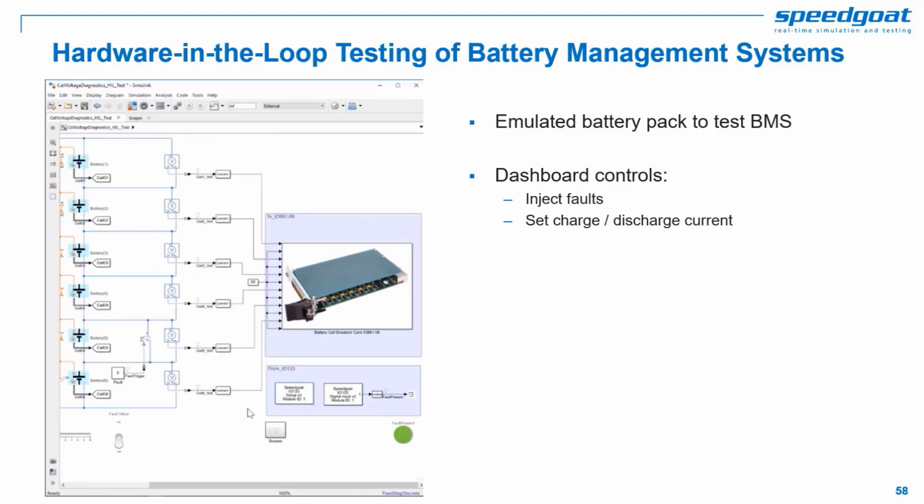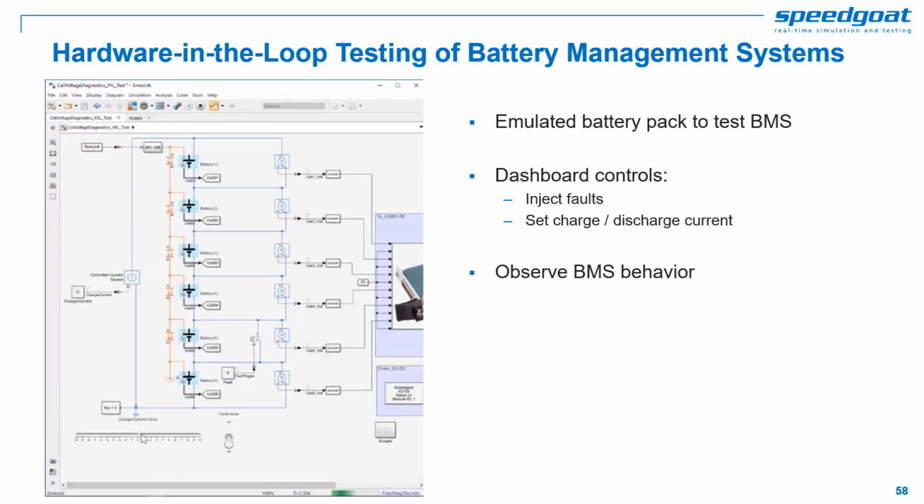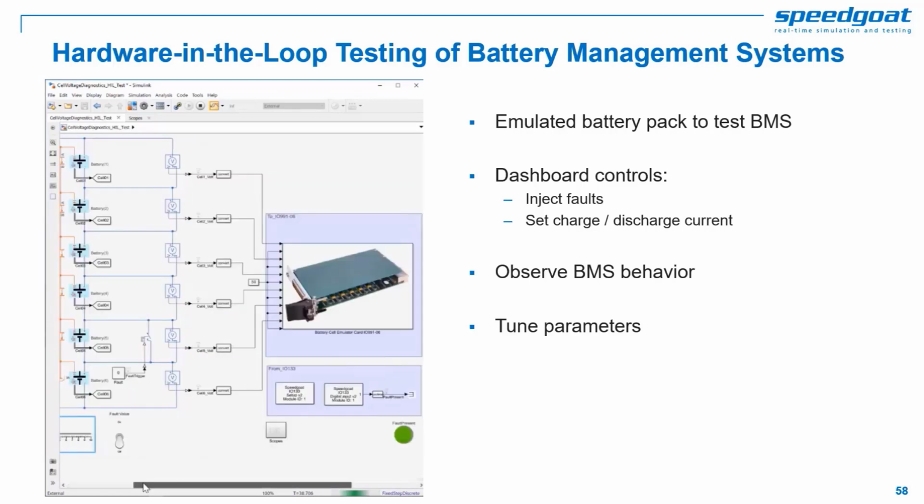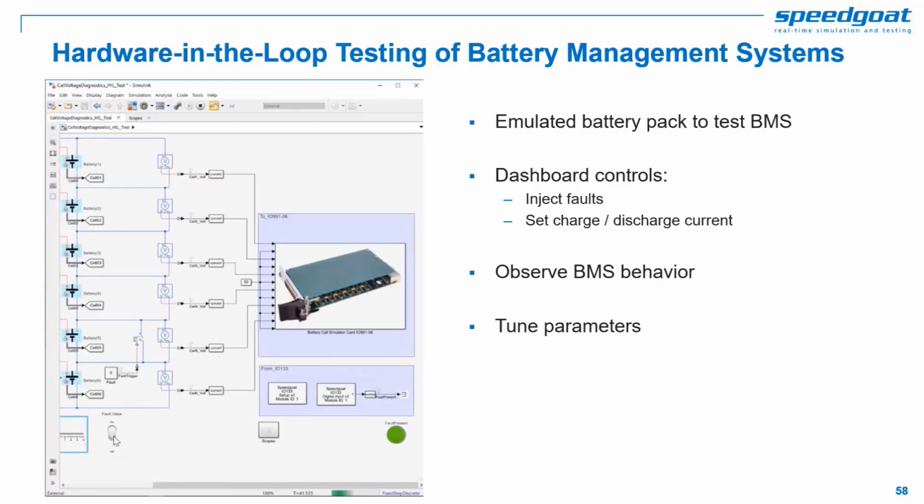To perform diagnostics on cell level, we measure the voltage between two cell terminals. The measured cell voltage values are sent to the I/O module, which converts the numerical values into voltage outputs, each relating to an individual battery cell. The BMS controller performs diagnostics on cell voltages and detects overvoltage and undervoltage faults and short circuits between two terminals. When we inject a short circuit fault, we can immediately notice the red warning light.